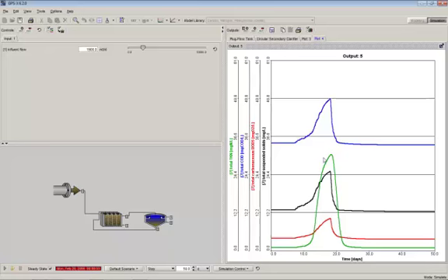So this is a dynamic simulation. You can do your own wet weather events. You can do your own dynamic stress testing and so on by entering in information here. You can either do it manually with your mouse, or you can even have GPS-X read in a file that will have a time series of information and will move that knob around for you.